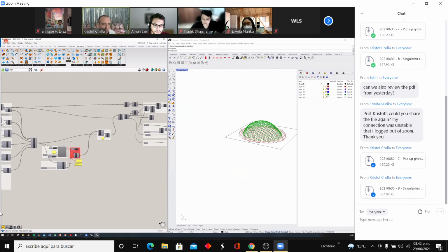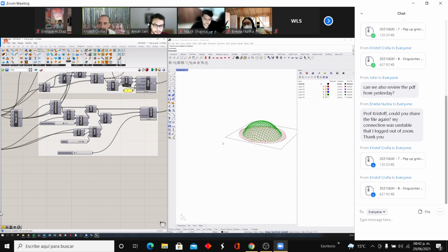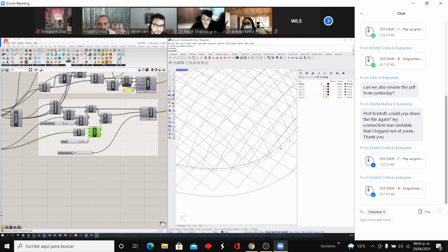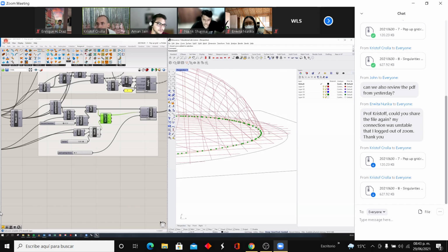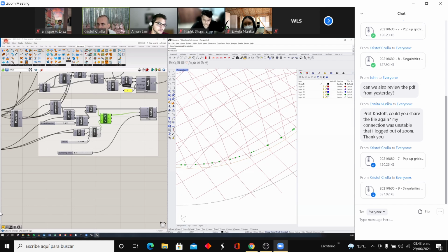Yeah, all good. Quick thing to point out: my scaled down curve, to which I am pulling with all my anchors. Remember how we're pulling all the points from our mesh over here to these points on the curve with a very weak spring force. So it's not a hard connection, and because of that we still have a relaxed edge. If you would make these points super tight and super hard, then your grid will distort quite a bit around the perimeter.